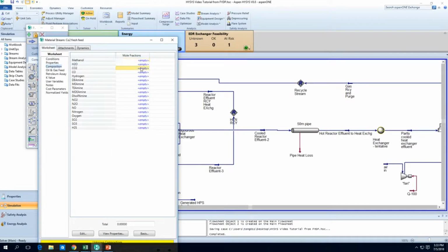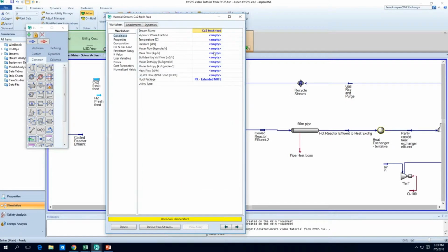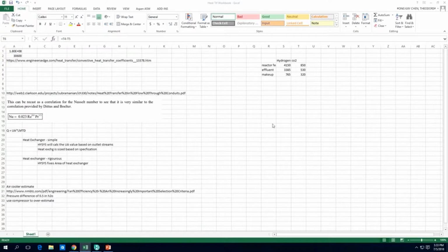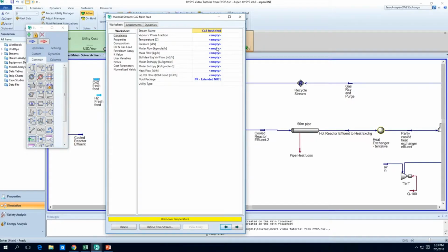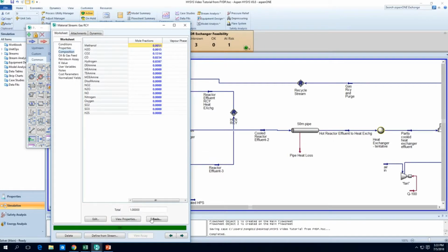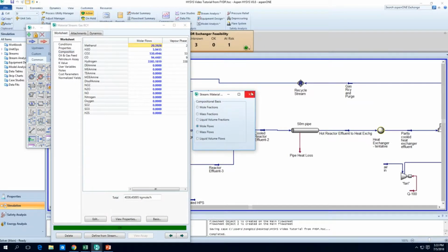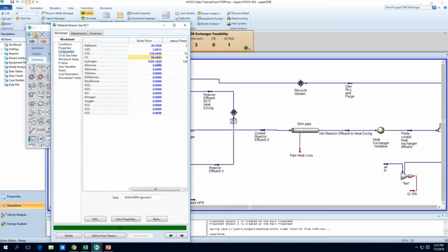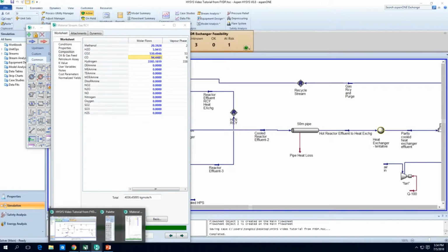This is CO2, so I'm just going to assume most of it or all of it is going to be pure CO2, and we need to put that molar flow rate, which I will put at 320 for now. And of course, since there's extra carbon monoxide in there, I'm skipping some steps here. There's some carbon monoxide inside there, which acts as a carbon source as well. So I'll need to add that in as well, so that I don't put too much CO2 into the system. So let's add 94 kgmole per hour of carbon monoxide into our equation here.